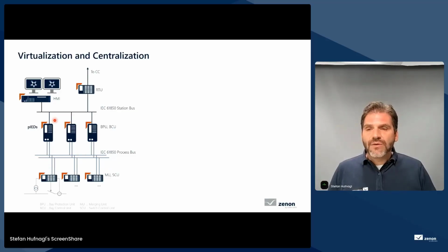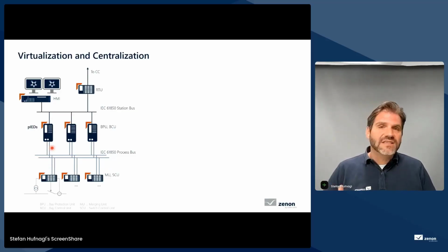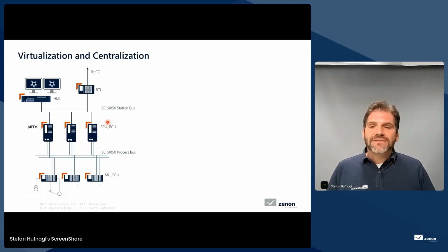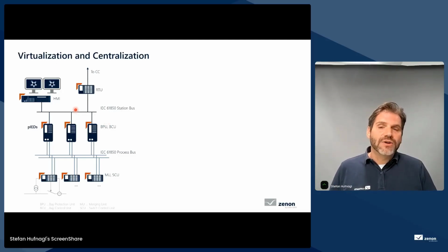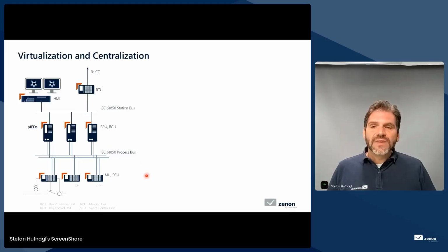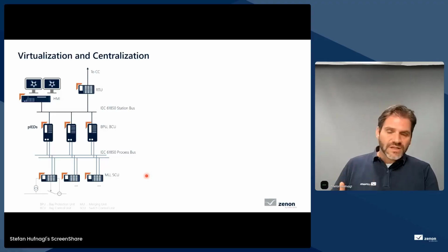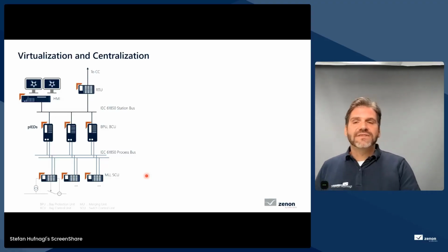Above that, we would have our physical IEDs, the protection devices, bay protection units, bay control units. And again, above that, in the IEC 61850 station bus, we would have a couple of higher level applications, such as HMI or an RTU, in order to establish connection to control centers. And here we can see that there are a couple of hardware devices distributed in the entire facility.